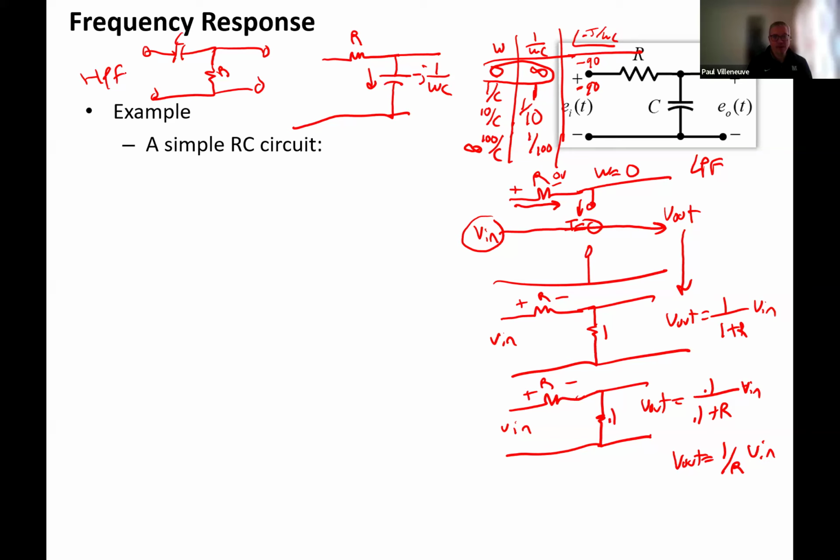You can use both. Yes, you can substitute inductors for capacitors, and it does change the low pass and high pass, so you do have to switch them around. But the reason we oftentimes don't see inductors is that there are millions and millions of different versions of capacitors available. For inductors, you can buy some, but they are far more limited in availability, because most of the time you just design it yourself, and they're pretty easy to build.